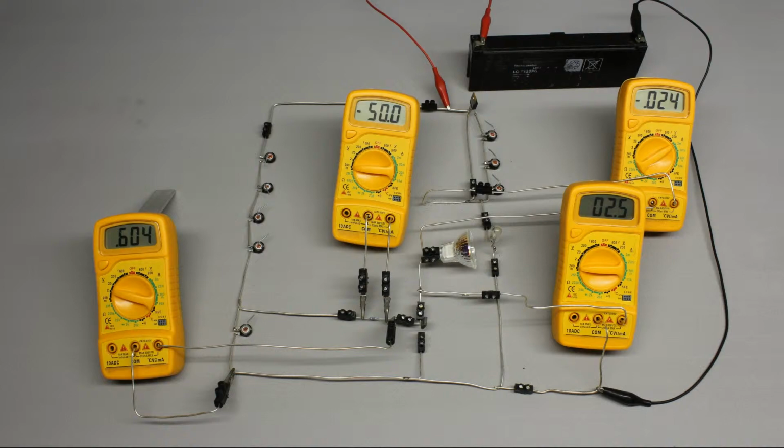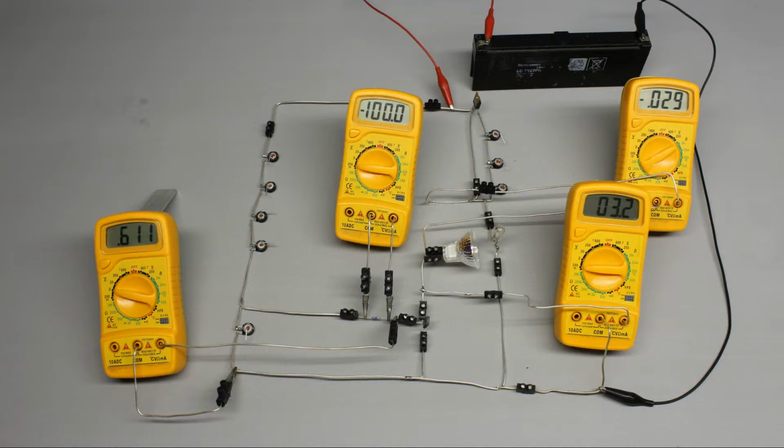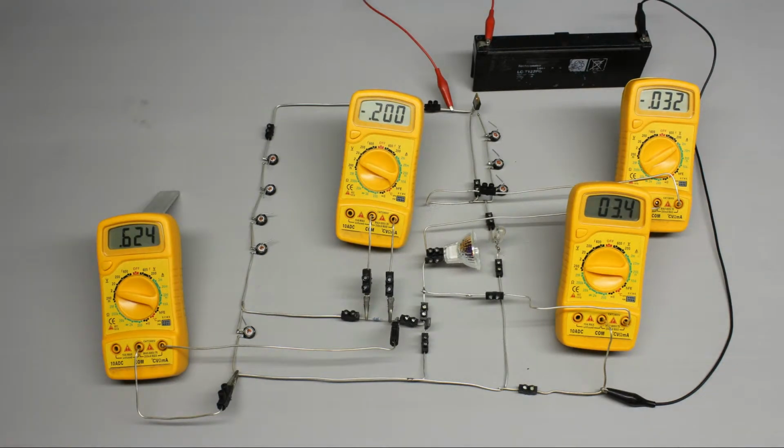Hypothetically speaking, we could also keep the base voltage at a constant level, but when looking at the datasheets of transistors, there's predominantly a constant base current given for the plots. 3 test series are recorded using a constant base current of 50, 100 and 200 microampere, which correlates to a voltage drop of 50, 100, respectively 200 mV at the 1 kΩ resistor.